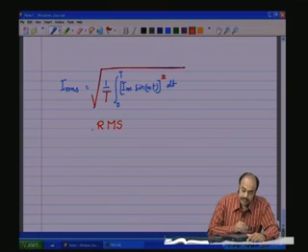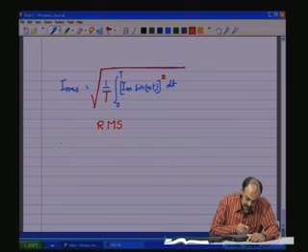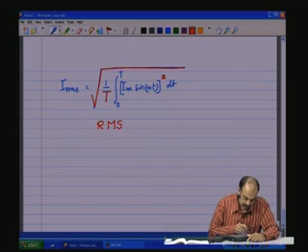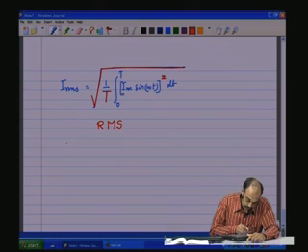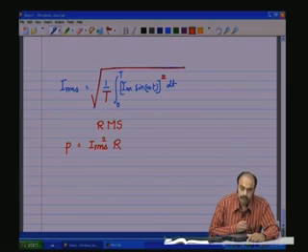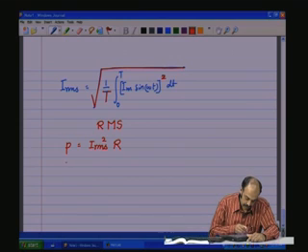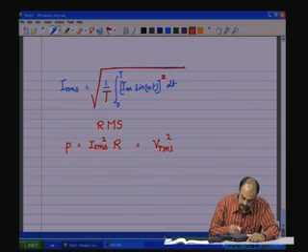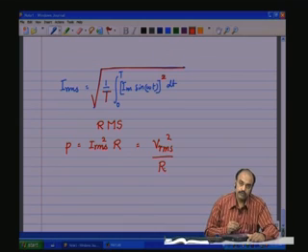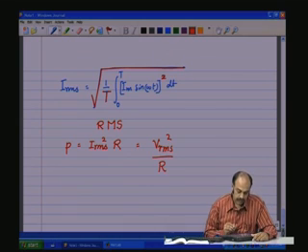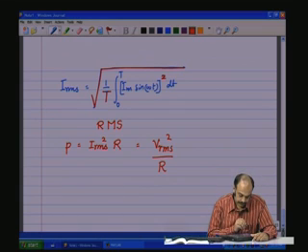So, that is what the RMS means, and that is the power generating component. So, power is equal to I RMS square into R always in the case of sinusoidal quantities, or it is equal to V RMS square by R if you are taking the voltage across the resistor.